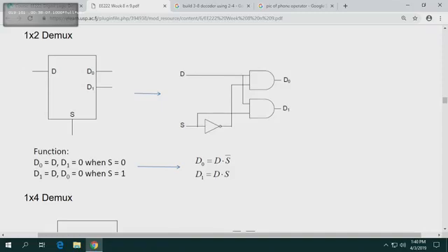So again, that's how your demux works. That's your block diagram of a demux. After every system, no matter how complex, even those PABX systems, you can reduce it down to AND, OR and NOT gates. AND, OR and NOT, 3 gates can build everything. And of course, those 3 gates you can build using what? NAND gates. So pretty much entire systems you can build using just NAND, or just NOR. Any questions, guys, for this one?